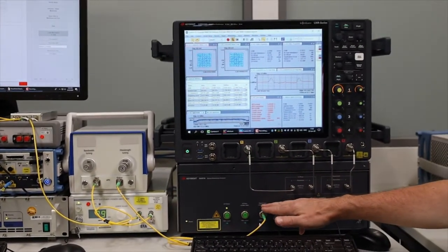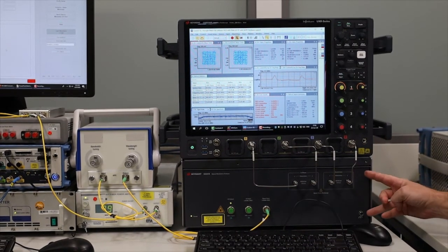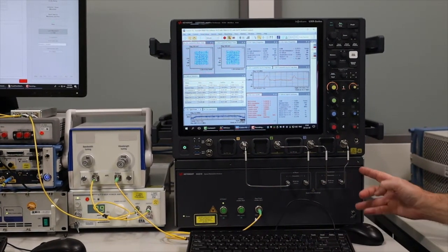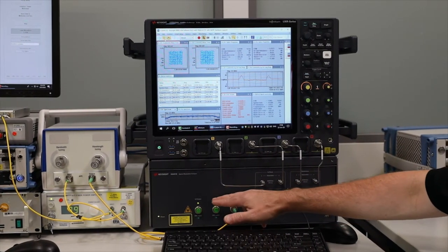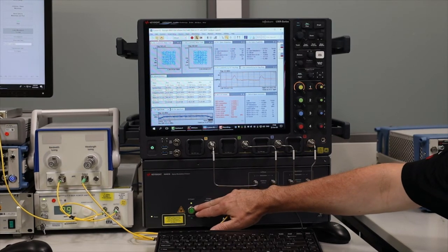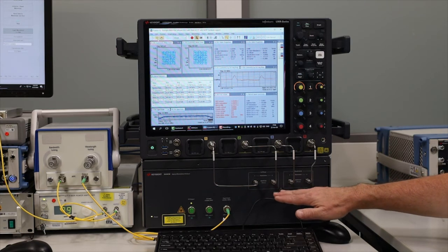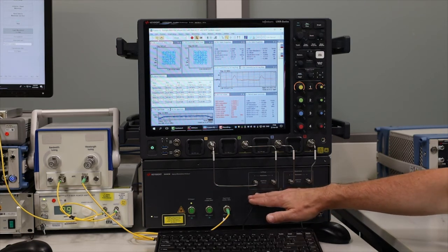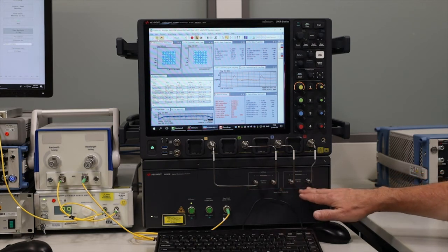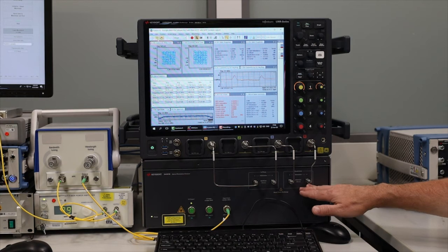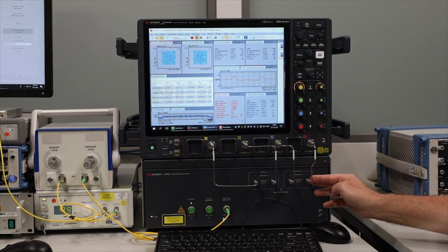Once the signal enters our optical modulation analyzer, we find in the lower box a complete coherent receiver. So there is a local oscillator built inside that could also be used for external experiments. There is an optical hybrid built inside that converts the optical signals into optical I and Q. These optical I and Q signals finally enter the photodiodes on the internal end of this setup here and are converted from optical into electrical signals.